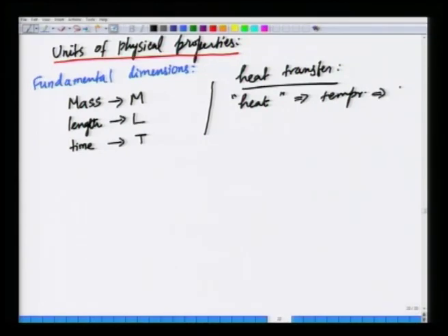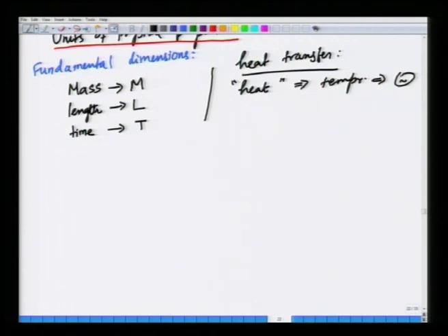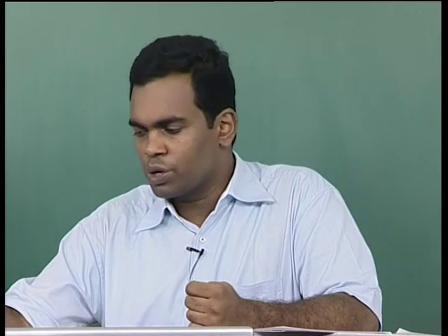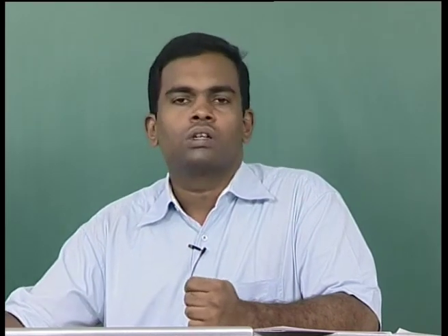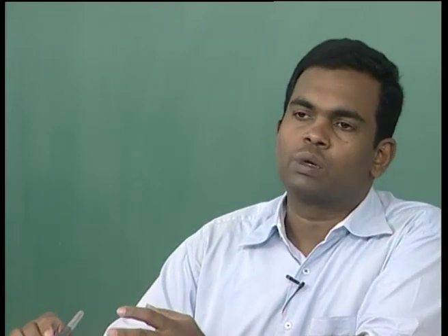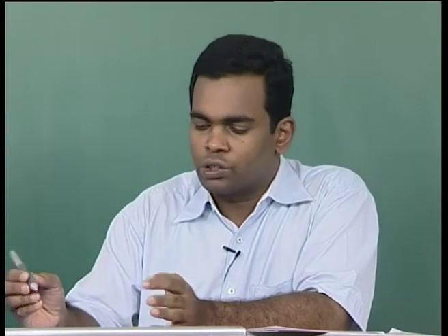This is an additional dimension, sometimes it is denoted by capital theta. Okay. So, these three are the fundamental dimensions in mechanical settings like fluid mechanics, while if you are interested in heat transfer and thermodynamics, you will have to invoke this as an additional fundamental dimension. Okay. So, while these are the fundamental dimensions, the dimensions of all other quantities can be obtained from the basic definitions of various quantities.